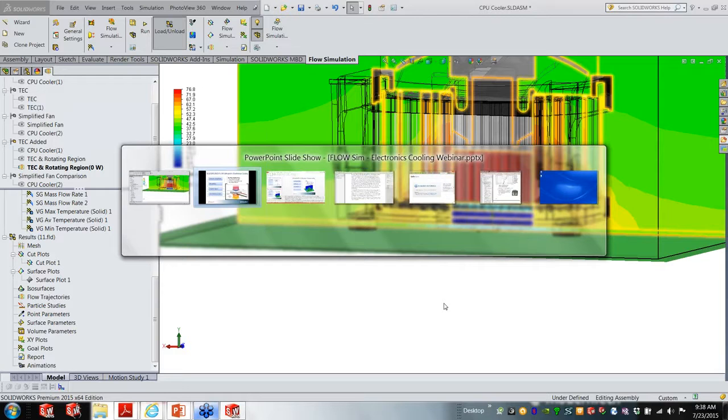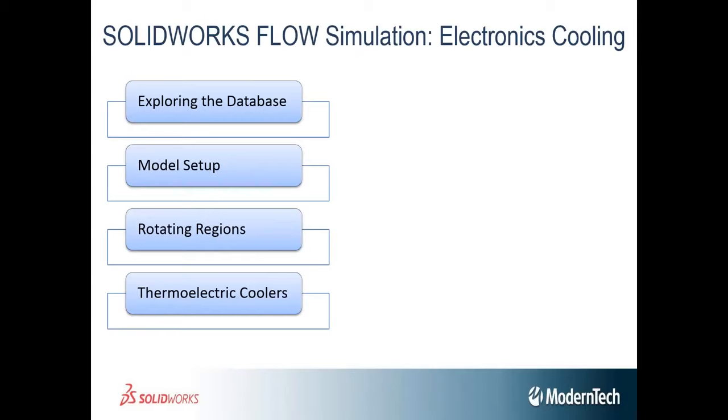Semiconductors at very low temperatures are actually more efficient. And so I actually had a problem in the past where we did a similar analysis. One thing that we actually had to deal with was condensation on the PCB because we got so cold that we approached the dew point of the air, and so we had to deal with humidity and air temperature at that point and figure out how to prevent condensation. So it's a pretty powerful way to dissipate heat, the combination of a heat sink and a thermoelectric cooler.